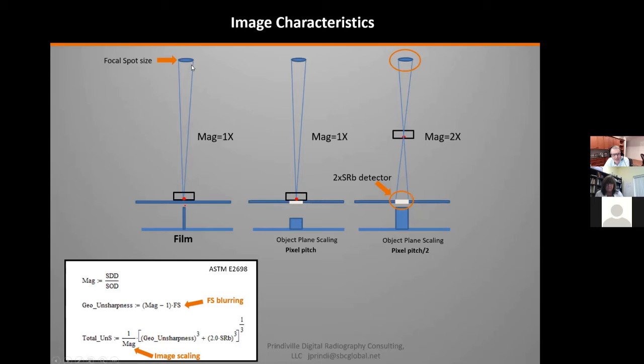Commonly we're going to take a film shot so that we don't get a lot of source blurring. Because as you move away from the film towards the source, you're going to get source blurring from the size of your source. So we don't want that. So we're going to be close to the film. It was very common to just take your shots right up next to the film so you can keep that high resolution. Because if I move away, I'm going to start to fog it. It's going to start to blur.